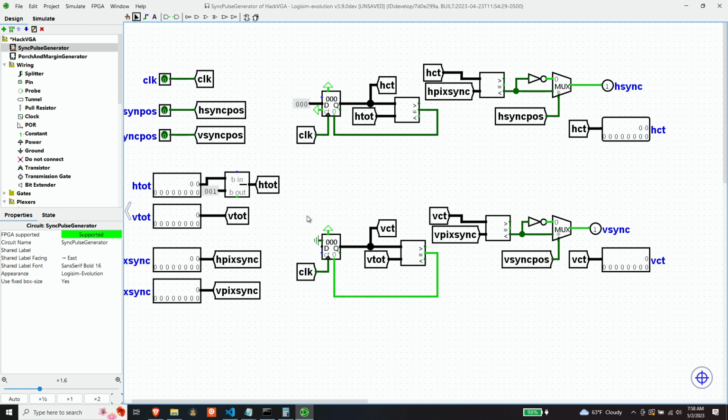So what you really need to know is, when are you at the last valid pixel? In order to do that, that's really why this subtraction was here. Although it's awkward for it to be here sitting off of H total, it really should be an input to this counter by itself. And finally, we're never going to load 0 back into this horizontal counter.